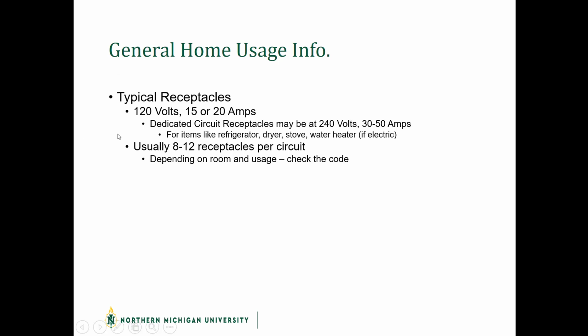So again, you should be able to plug in 8-ish, to 10, even 12 here, depending on the use again, but you should be able to plug in and use 8 or so receptacles on a circuit at any given time, given that you're probably not going to be plugging everything else into other circuits at that same time.